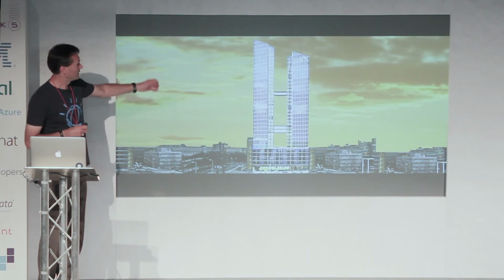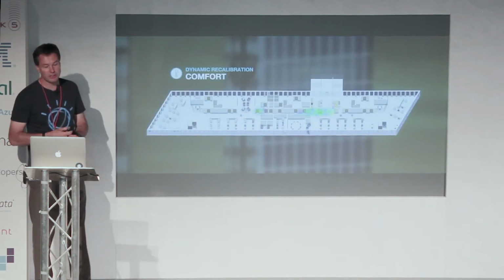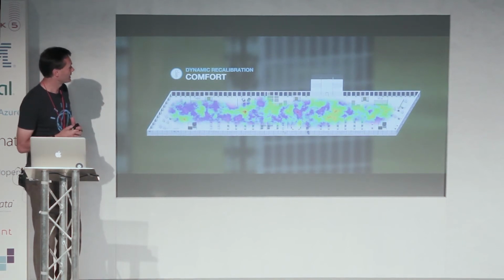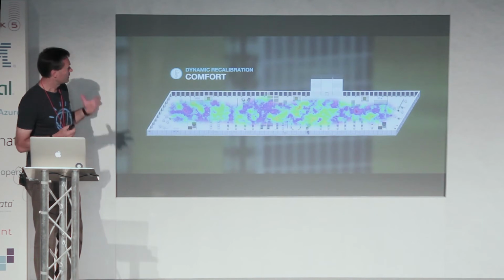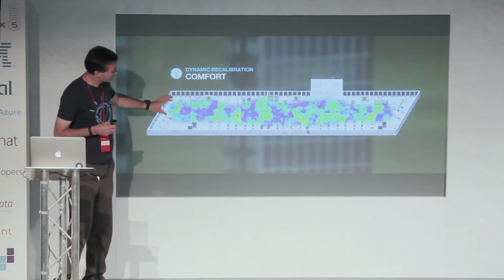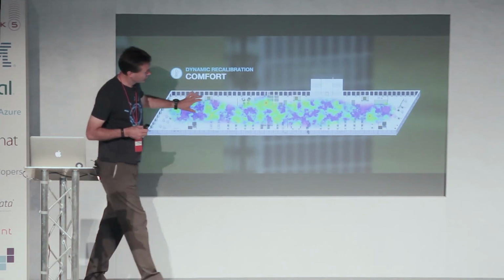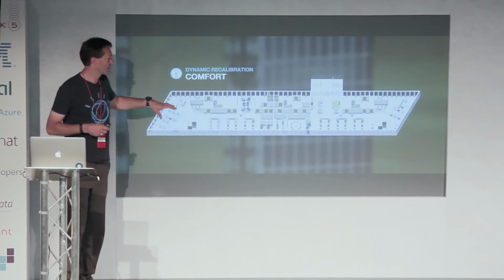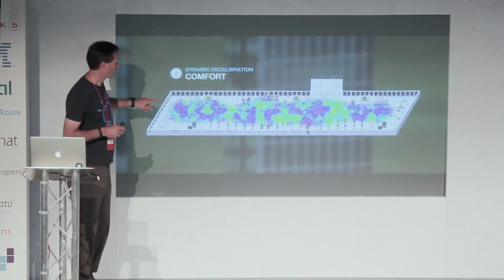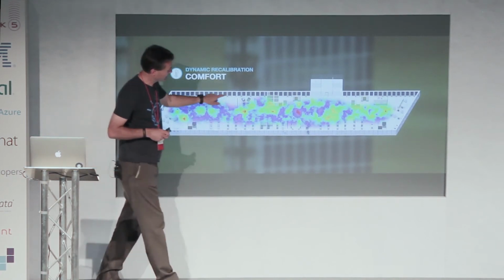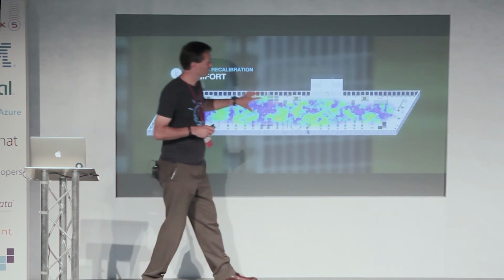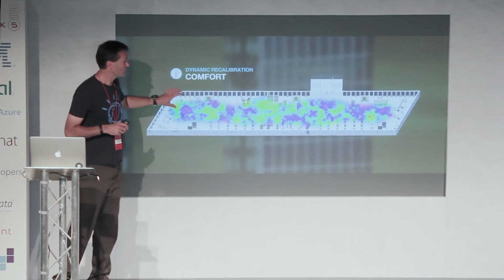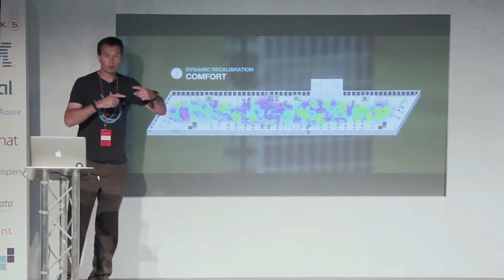This is our lovely Highlight Towers building in Munich, the Watson IoT Center. And we've made that into a digital twin showcase. A number of dynamic dimensions to that. One is for comfort. So we've got a thermal model of each floor where we think, based on what we know about the heating and cooling system, what the temperatures should be. And then we've got heat sensors all over the floors, measuring the actual temperature to give us the ground truth as to what the real temperatures are. And then we can tune the model so it's more reactive.